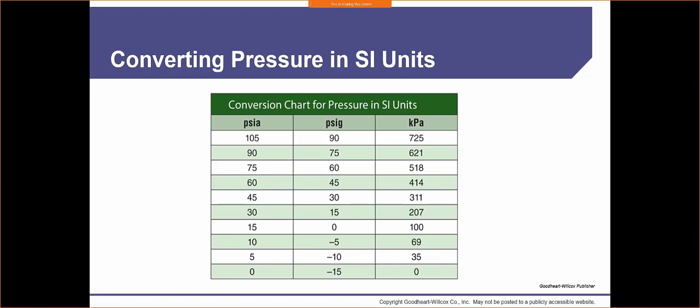All right, so it's the same thing when we're talking about pressure. All right, we have that 14.7. They're rounding it up to roughly 15. We're taking that 15 pounds per square inch and we're subtracting it. All right, we're zeroing it out. So that way we're really left with only 90 psi. Okay, and the same applies as our measurement decreases, so does our psi atmospheric. But we're always noticing that there's a 15 psi difference between one and the next.